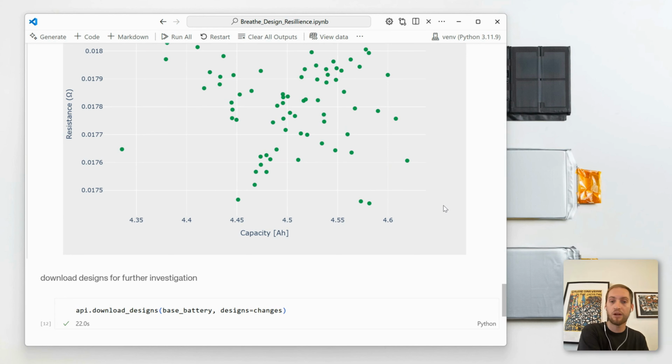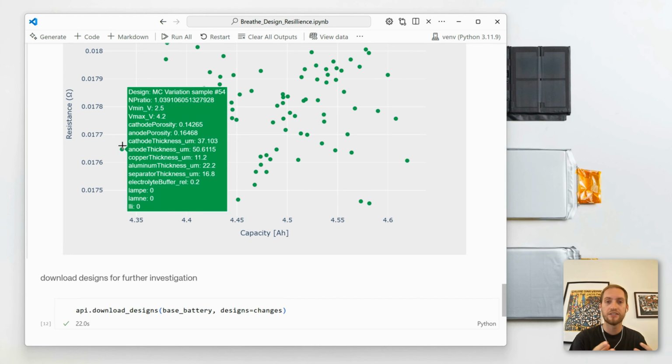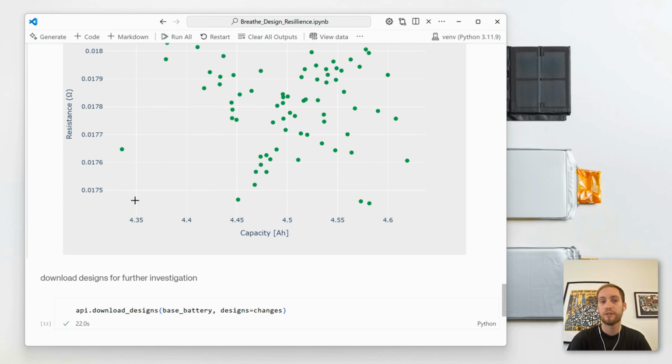I can refer back to that probability to populate my pack simulations with this, or I can check my validations if I'm doing SOC estimation. I can extract some of these different edge cases, common, less common, super boundary condition like this one over here, and take a look at the accuracy impact I might get on my SOC, because in theory, this is a cell that would go into production because it passes the criteria from the supplier side. And as a result, make sure that the user experience is guarded.